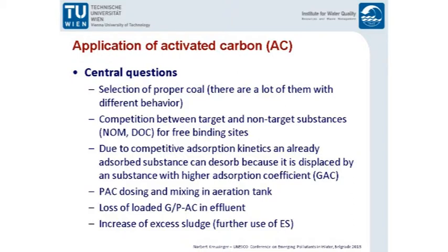We can lose activated carbon to the effluent, so we have a highly loaded powdered activated carbon particle, highly loaded with micropollutants, and then we lose it to the environment, to our surface water, and then some macrozoobenthos organism feeds on that, and now it has this highly loaded particle incorporated. So we have to prevent the loss of those very small particles. Those are technological challenges that are now investigated worldwide to overcome those problems.